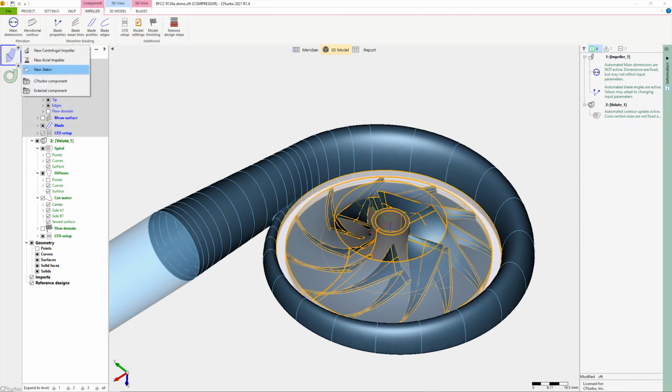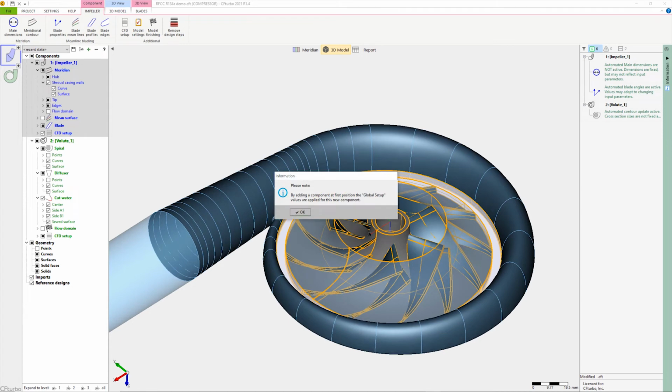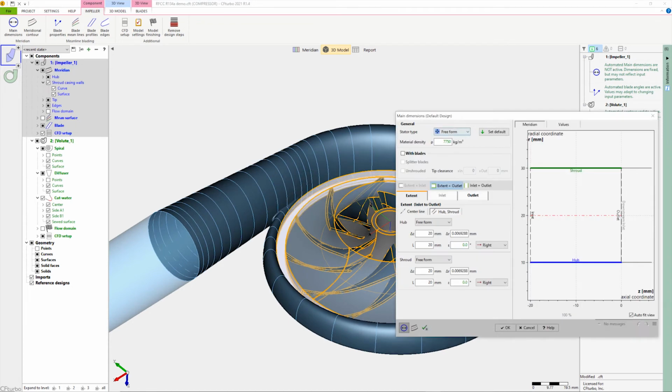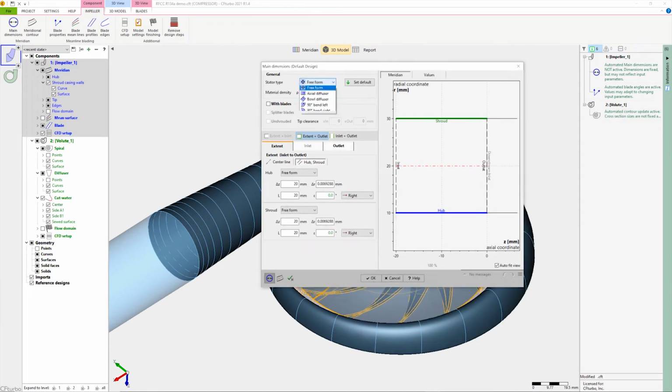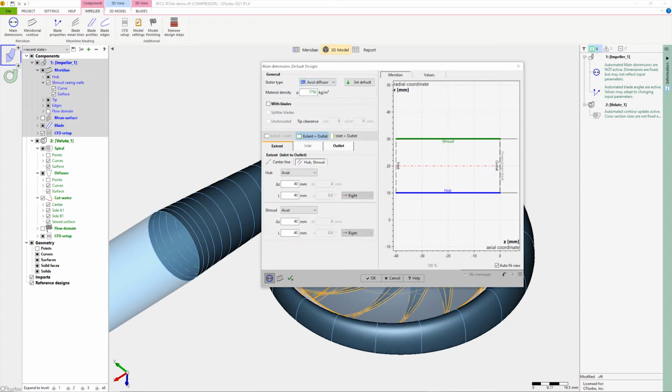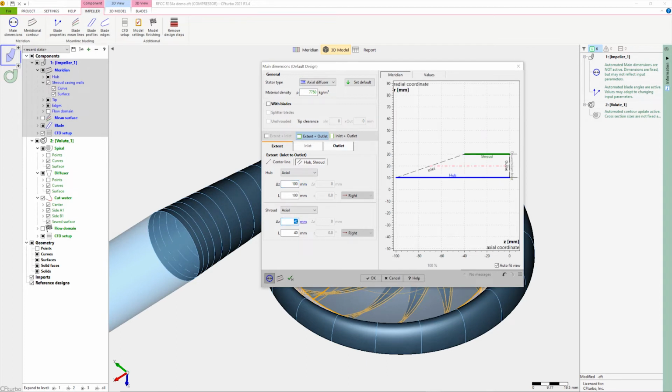To finalize our compressor stage and prepare the CFD simulation model, we add a pipe on the impeller's suction side. Likewise, for numerical reasons, the inlet pipe should have an appropriate length to minimize the inlet boundary's impact on the compressor impeller. In this specific case, we add an inlet extension of 100 mm.